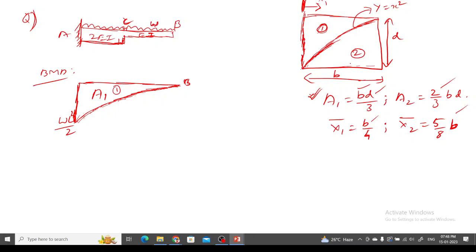Yes, sir. And in the left hand side diagram, SFD will be a rectangle, positive. SFD, I don't think it will be a rectangle. It should be like a triangle, I think. Yes, sir, it should be a triangle because the load intensity is constant, so the slope should be constant. If the SFD is a triangle, then you will be having a slope of 0.